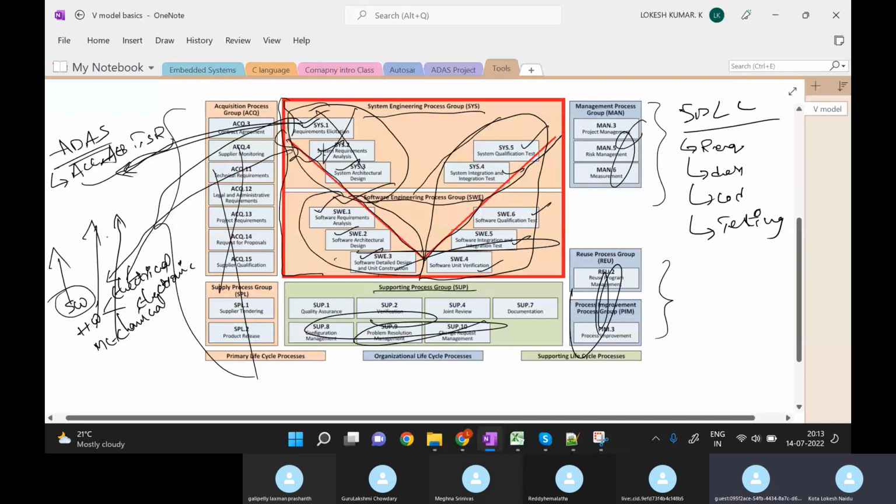So in case of hardware, again, what kind of microcontroller is needed. If it is a microcontroller, how many bits, 16 or 32 bit. If 32 bit, how many CAN channels it has to support, how many Ethernet channels it has to support. How many ADC channels it should have, how much memory it should consume. So all this analysis is the requirement analysis. Then the system requirement analysis will go a little bit more into detail. So this is a microcontroller of so and so family. It should be a 32-bit microcontroller and memory should be 16 MB. And this is for the hardware level.